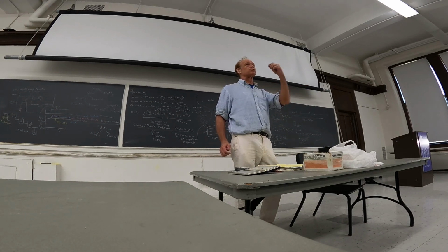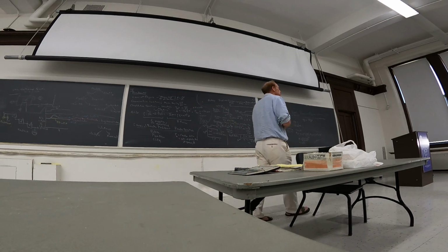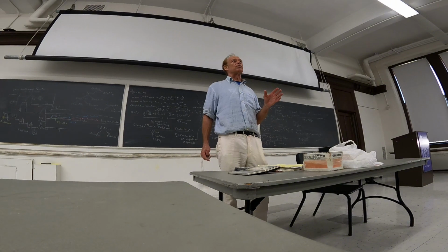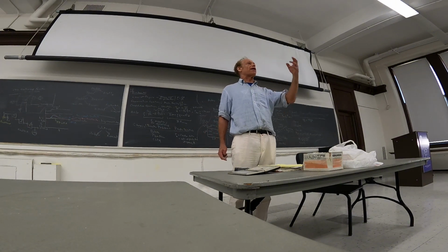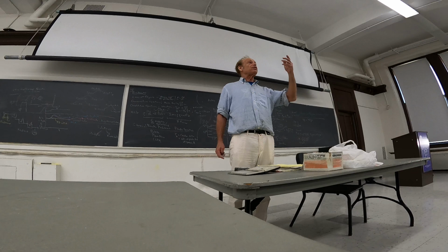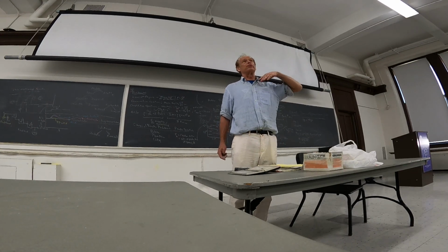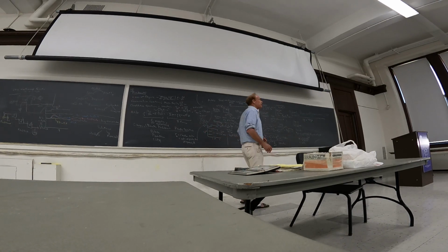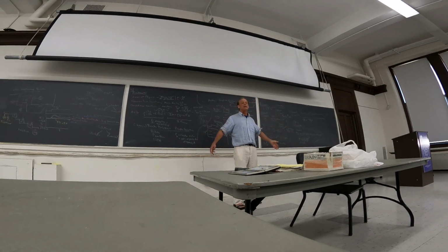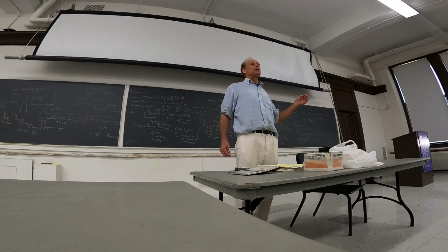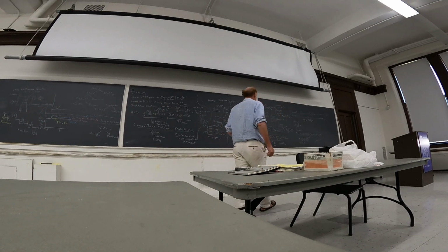So one reactor volume's worth of fluid. This has become actually quite important in COVID days. What COVID people talk about is how many air exchanges there are per hour in a room. The inverse of that is how long it takes to change all the air in the room. So how long does it take to change all the air from the ventilation system? Tau. So the COVID people don't call it space-time, they just discovered it now. We've known about it for 100 years. We call it space-time. Tau.